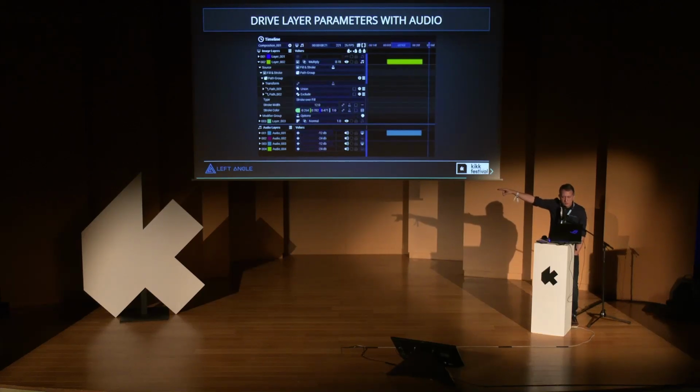3 or 5 audio sources into the bottom stack, you can mix them. And on the upper stack, you can add an analyzer, a spectral analyzer, to say, okay, in this mix down, which is done on the fly, it's not pre-rendered, I want to only take this frequency band, and use this frequency band to drive a rotation, a position, any kind of parameters. Okay, so you don't have to create keyframes to make the analysis. It's done in real time and on the fly.